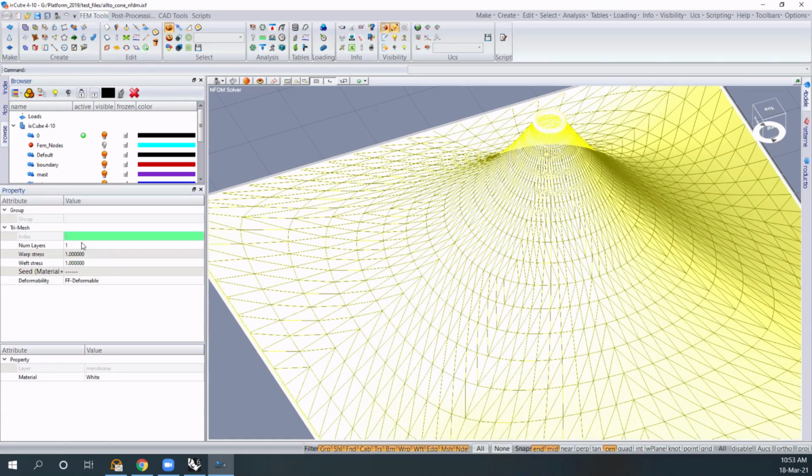If you try to do this using the force density method, you don't see any property on the mesh because they are not finite elements. Now we have switched the method, we have deleted the links, and we have moved it to the natural force density method. And now the meshes are finite elements. We are going to do the form finding using these as the finite elements.